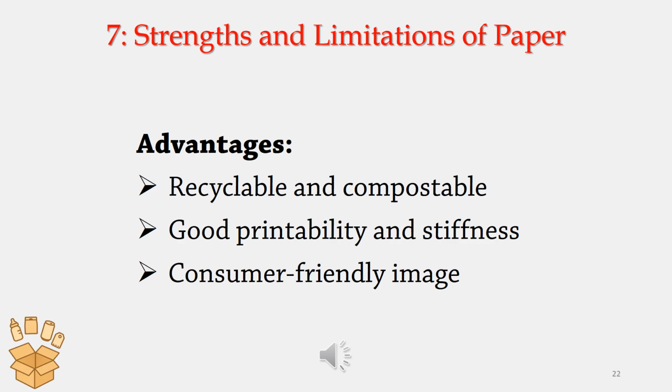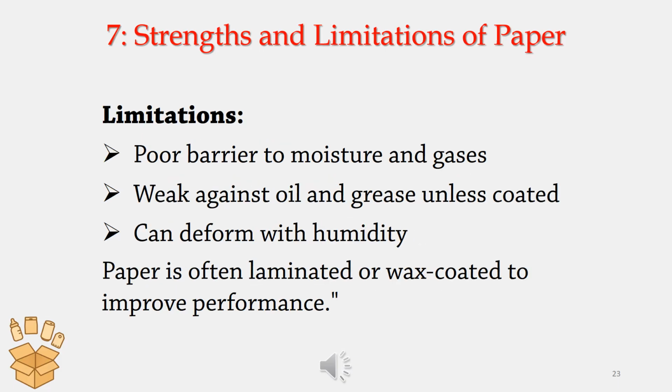Strengths and limitations of paper. Advantages: it's recyclable and compostable, has good printability and stiffness, and a consumer friendly image. Limitations: poor barrier to moisture and gases, weak against oil and grease unless coated, and can deform with humidity. Paper is often laminated or wax coated to improve performance.